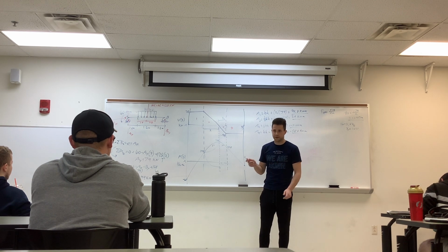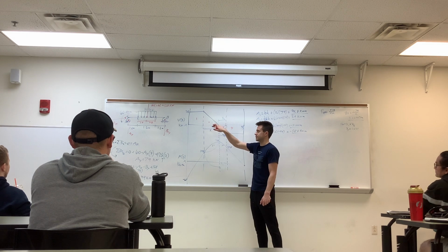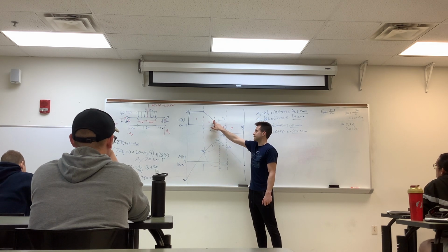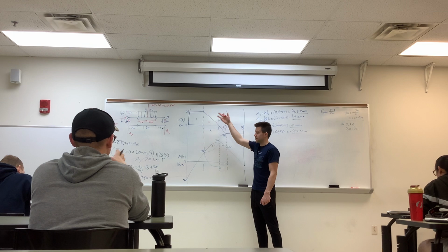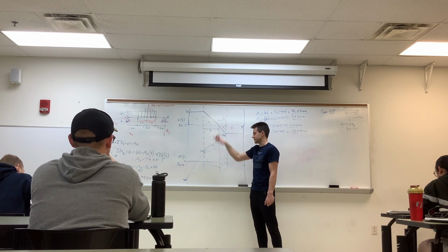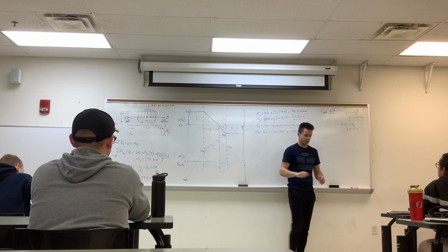Correct. You're thinking about it as a distributed load. So if it's a rectangular distributed load, the nature of the shear diagram will be linear. If it's triangular, it'll be squared, which makes the nature of the moment diagram cubic.